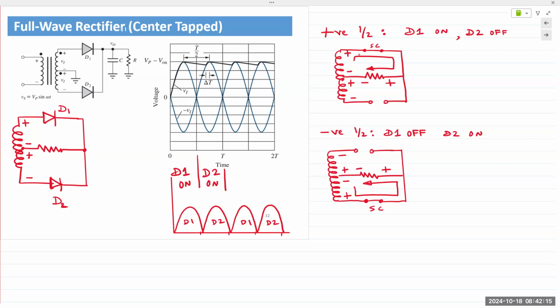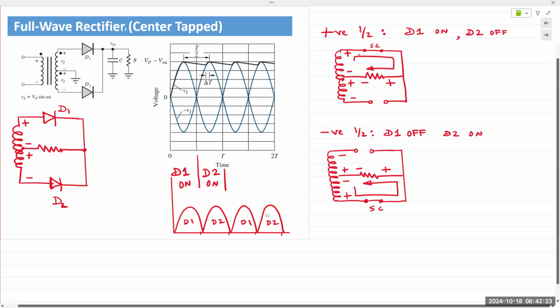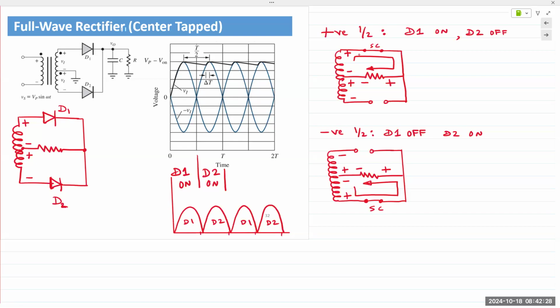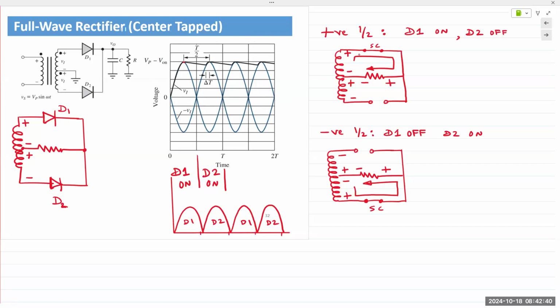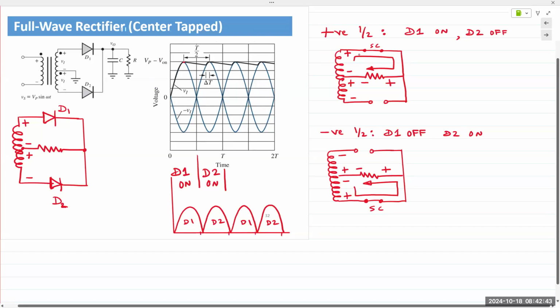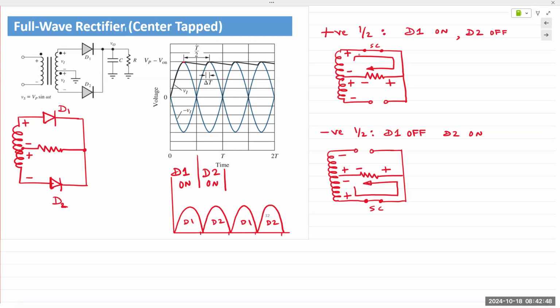Yeah. And since you're on the topic of capacitors, let's talk about the filtering a little bit. So you have a capacitor connected at the output in parallel with the resistor. I'm hesitant to throw a lot all at the same time, but let's say you have this waveform that's coming in at the output. I'm talking about this image right here. So you have this waveform coming in. Capacitor is connected across the output. The same output is going to the resistor and is going to the capacitor. Okay, capacitor starts charging.